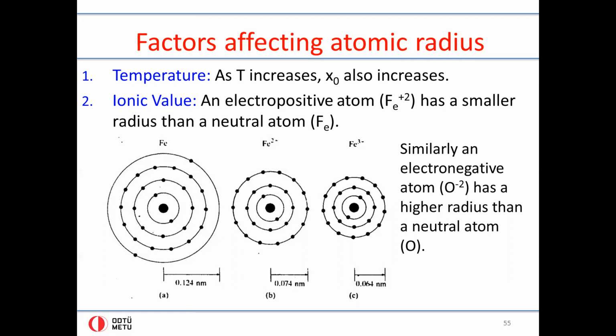So as temperature increases, the atoms are energized, and because of this, they vibrate more, and because they vibrate more, this x0 distance increases. The x0 increase can be thought of as looking at the energy versus x curve. You move up along the curve and in the positive x direction, hence x0, or the stable condition, sort of increases. Or you can think of it as the atoms get energized, hence their radii increase, hence the summation of the two radii and the bond length increases.